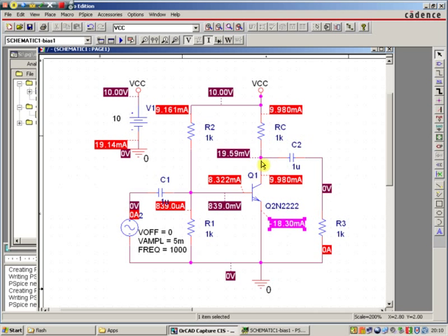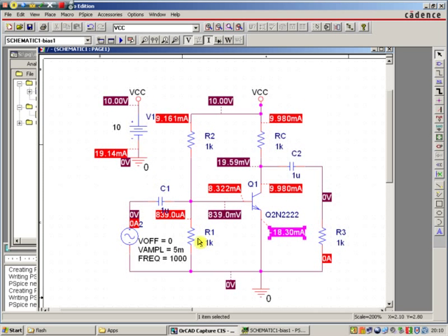What we would need to do to design this circuit is to put the collector at the correct DC voltage and then set these two resistors in the bias network so that they operate correctly. You've just done a bias simulation for this circuit, so you can see what's happening. In another bias analysis, I'll actually show you how we would change things, and just by intuition